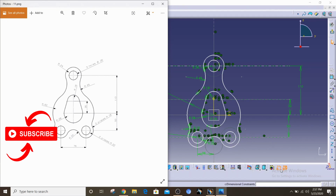So this is basically how you use symmetrical properties and curves. Basically what you have to do is, like always, just look for symmetrical properties in these sketches, and if you see any curvy object, this is how you basically do it, because this is completely curvy. There's no single external straight lines here. So just make use of these tangential properties to join the two circles smoothly, and yeah, just try to use symmetry in your sketches as well. It's going to make your life a lot easier.